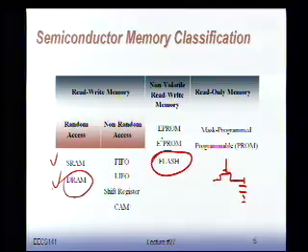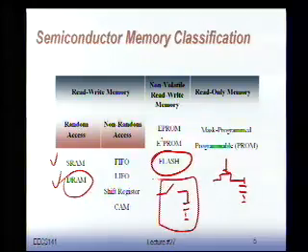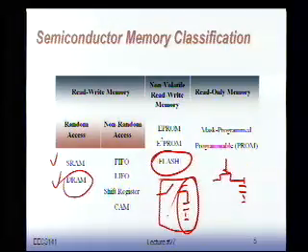The problem with DRAM, as I mentioned, DRAM is a capacitor, right? You put charge on the capacitor, and that's a 1, and there's no charge on the capacitor, it's a 0. Now, to make a good DRAM, I need a lot of capacitance. To make a good storage element, it's nice if the capacitance would be as large as possible. So making a large capacitor on a chip is not easy, because if I would do this in the traditional way, the way I design today,